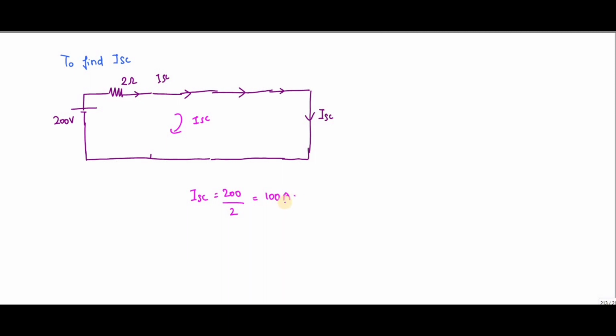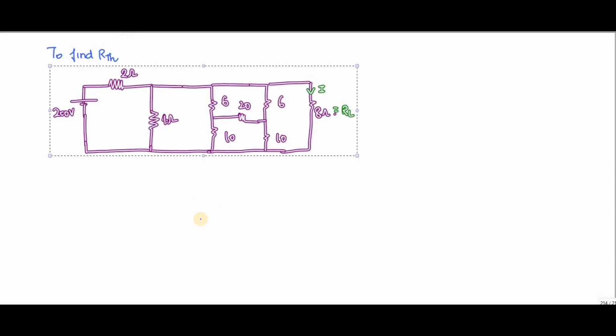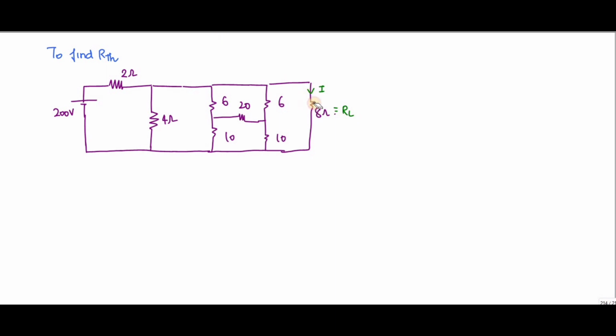Next I need to find the value of RTH. To find it, you take the whole circuit again and remove the load.